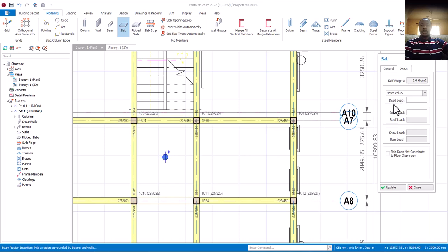But why are we now having dead load again, knowing fully well that self weight is also part of dead load? What this place is only talking about is the additional load that will come on top of your slab, and there's no other load that will come on top of your slab than your tiles. And the value for tiles or terrazzo, we use 1.2. And apart from that 1.2, we also have what we call a partition load.